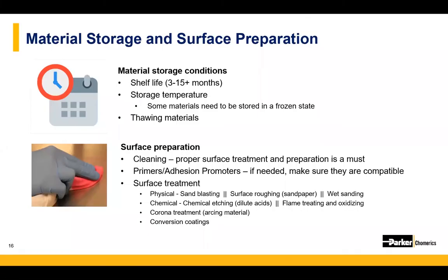All right, so before you order your conductive material, you need to know how the materials can be stored, how it's going to show up on your shelf or onto the doorstep here. Shelf life can be pretty varied for materials. You need to know how long you'll have until the materials expire and they won't meet those original specs. Also, some compounds need to be stored in frozen or cryo conditions to slow down the curing process and prevent from hardening before it's applied, meaning you're not going to be able to ship these on a Friday over a holiday weekend on dry ice.